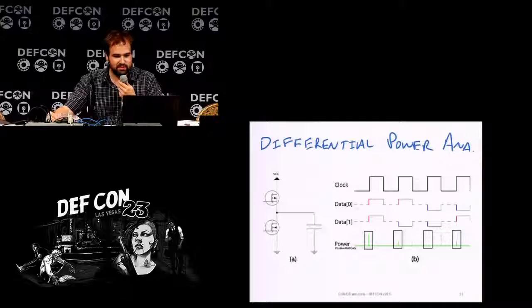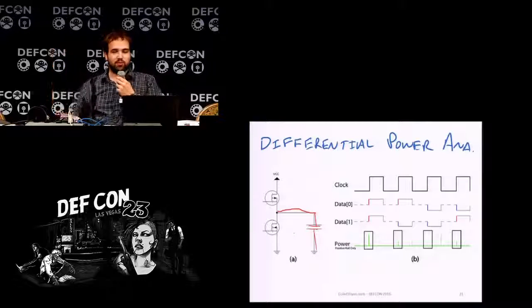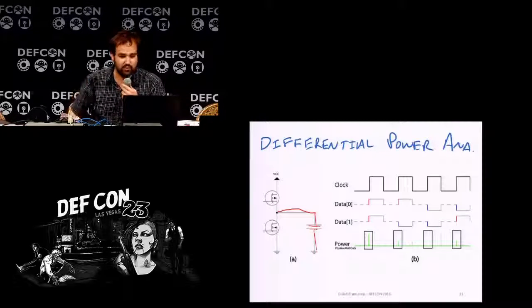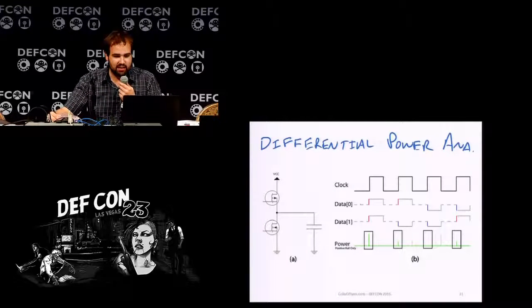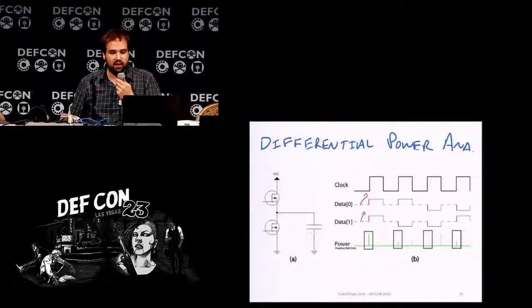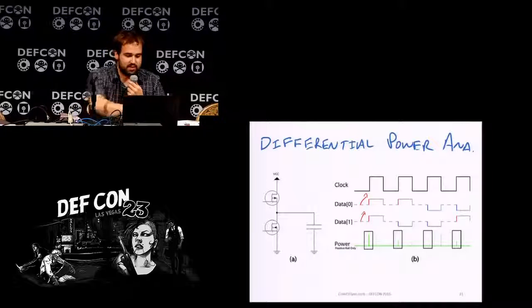And this uses a really simple idea: inside the microcontroller, we have these data lines, which are just long wires, and effectively a capacitor. If you remember vaguely from high school physics, changing the voltage on a capacitor physically takes a charge. It takes power to do that, even though it seems like a tiny, minuscule thing. In the microcontroller, setting a data line from 0 to 1 therefore takes more power than not setting it. If we set 2 data lines from 0 to 1, it takes even more power than if just 1 data line was set.